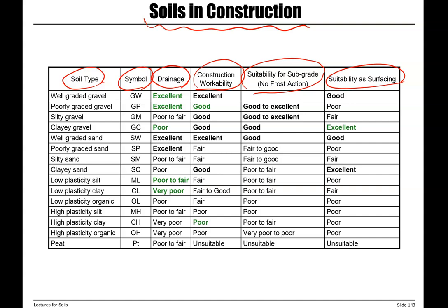Just remember that when we have well-graded larger particles, it provides better drainage. So coarse material, better drainage.